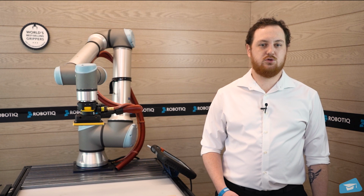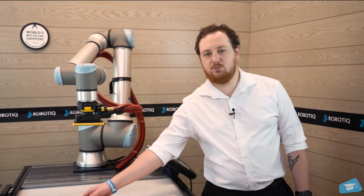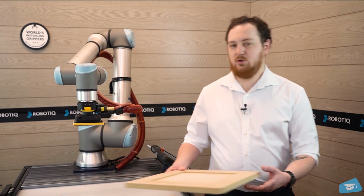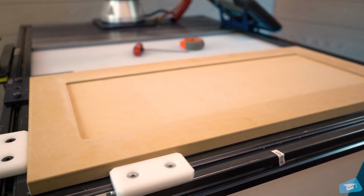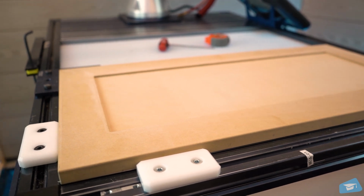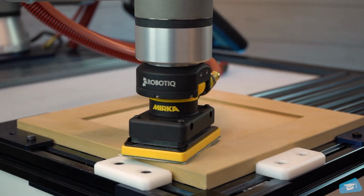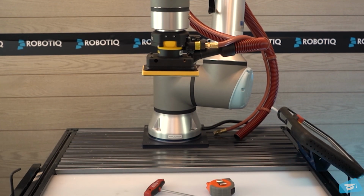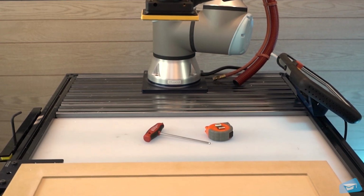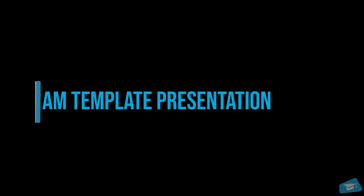Here's a few tips to make sure your sanding application will work properly. When processing various parts, one of the corners must always remain in the same position. It will be the reference corner for every cabinet door. Mechanical stops, like these ones, should be placed beside this corner to ensure that it will always stay at the same position. In order to minimize error when sanding parts of various lengths, always use the biggest parts to teach and adjust the program.